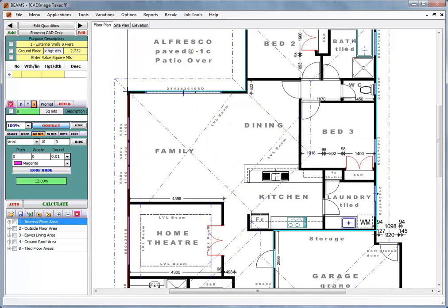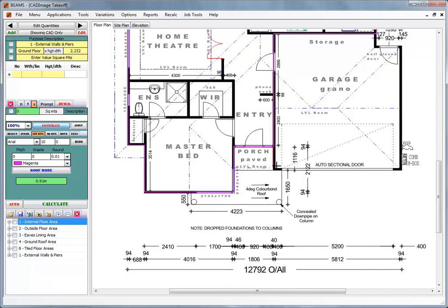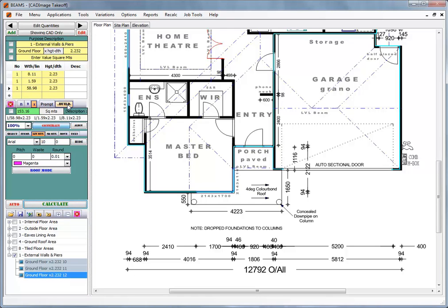Now, because we've got to the end, right click stores the value, but there's still more to measure. We can simply start another line. Every time we right click, the value is stored in the list. We need to highlight all three records using the shift key, calculate, build.